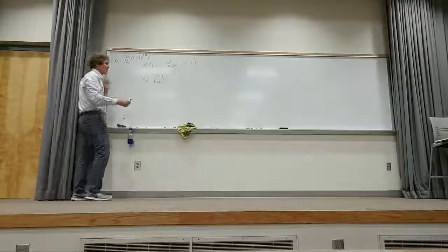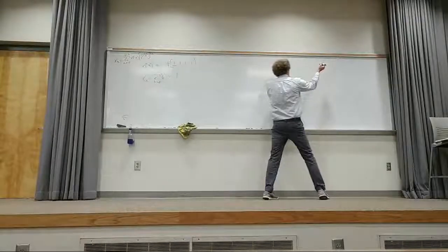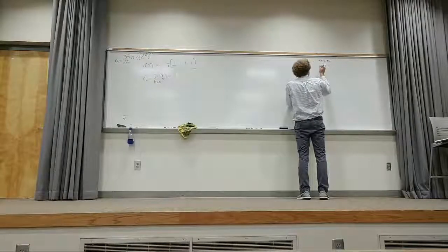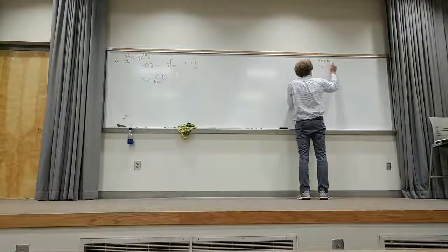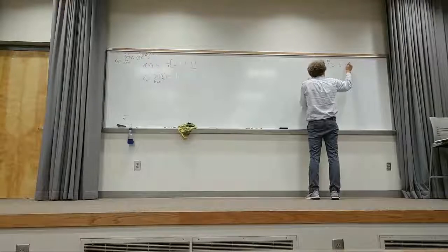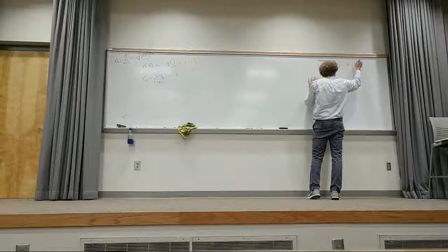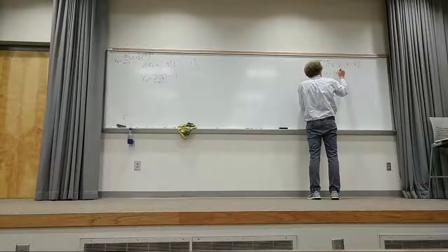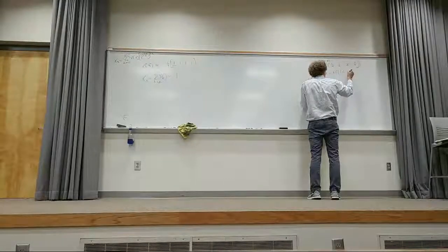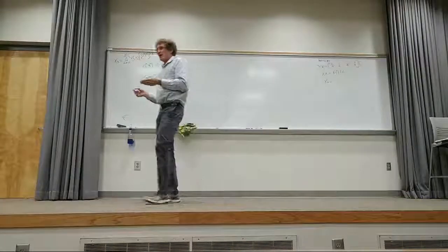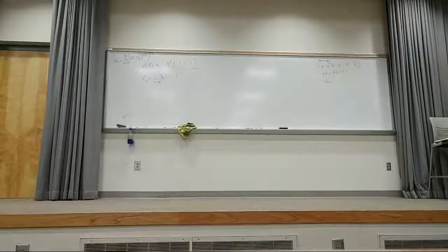If you want to know what this is, on MATLAB, you can just do this. Over here, this is with MATLAB. You simply type x equals brackets 1/4, 1/4, 1/4, 1/4, and then capital X, you can call it xk, equal to FFT of x, and you'll get it. It'll show you xk equals, and put these things down. That way you can test it. Does anybody have MATLAB on your computer now? Well, you can check.